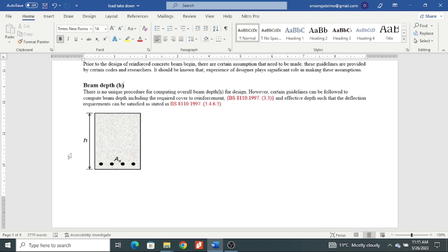I saw it in the Eurocode 2. Or you can even do pre-stressing of your beams, where you stress your reinforcement before you do your casting. Or sometimes you also do post-tensioning of your tendons so that you can make the beam stronger. So everything is possible if you sit down and do the math behind it and prove from the math that either it's possible or not, or if it's possible, these are its specifications. So let the effective depth not limit us in providing certain depths.